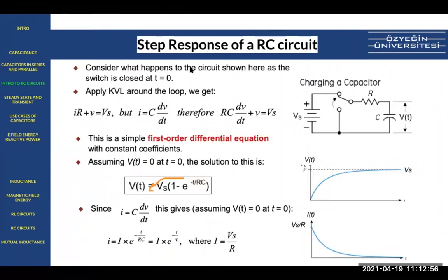The important thing is, don't forget that we are still doing the nodal equation. So when we have the circuit connected through the switch, IR is the voltage drop here, V is the voltage drop on the cap, and then we come back to VS, the voltage of the source. And what we do is we write the current in terms of the cap and voltage right here, right?